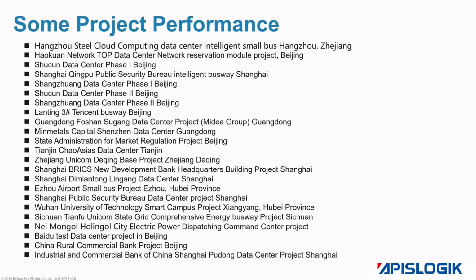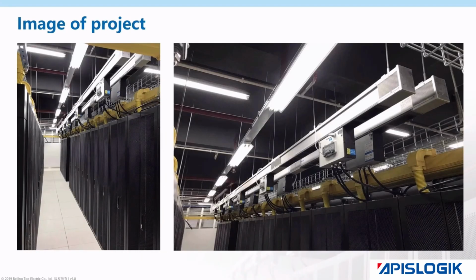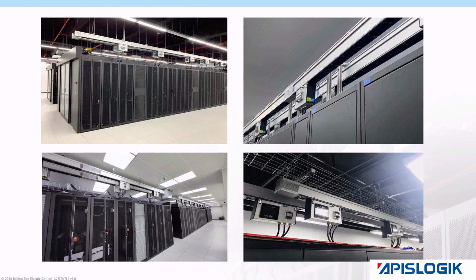The above are some project cases. The following are some live pictures of the busbar data center, which is a case of ceiling-mounted busbar installation. The busbar in the upper right corner picture is installed on the top of the cabinet, which is suitable for the situation where there is no hoisting condition, and the installation will not be affected by the environment, but this installation method will be more troublesome if it encounters a wall column.